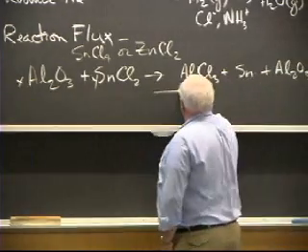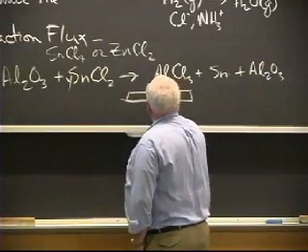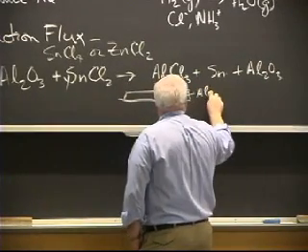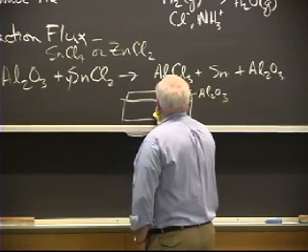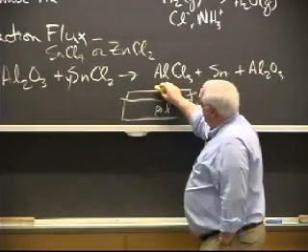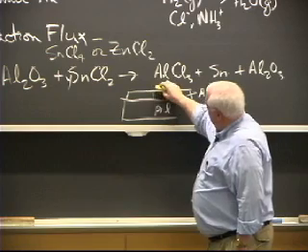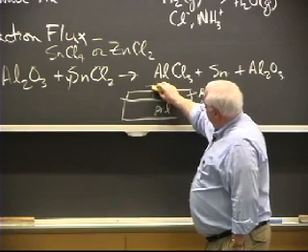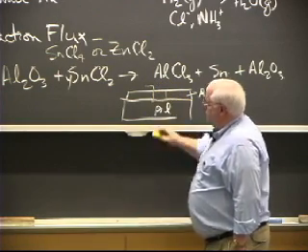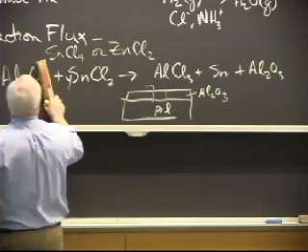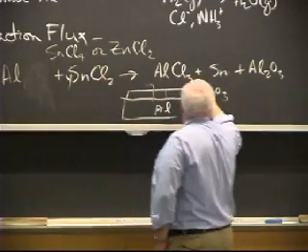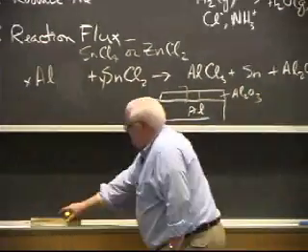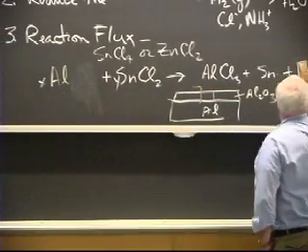What it does is, if I've got this layer of aluminum oxide on the aluminum metal, as you heat things up, you actually form little fissures, and the flux will get down in here. I'm sorry, I wrote down the wrong reaction. Here we go. It's aluminum metal plus tin chloride forms aluminum chloride plus tin.